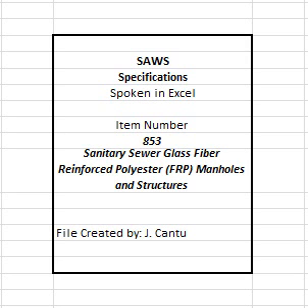After curing, the manhole and structure flow line elevation shall be verified by a licensed surveyor in the state of Texas, and a certified report submitted to the inspector prior to payment and uploaded to CPMS. Furnishing and placing all materials necessary to complete the work is included in milestone 1 and must be completed prior to payment, 40%. B. Milestone 2, 40% of LS, manhole and structure riser installation and flowable fill, up to 1